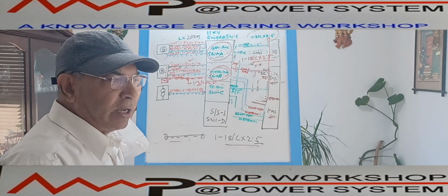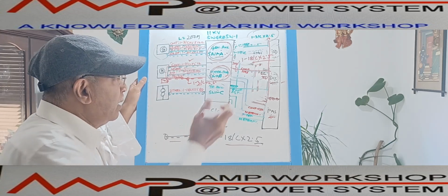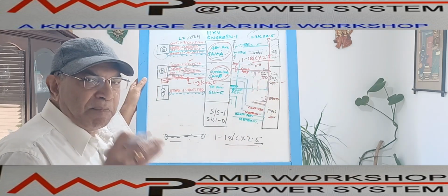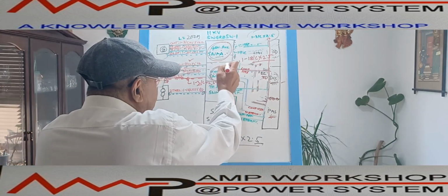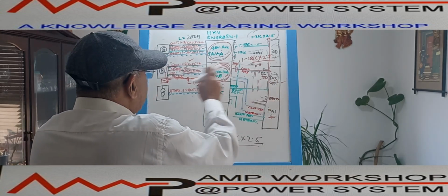What will this cable carry? It will carry breaker on-off control from the DCS, as well as various statuses of this particular panel, whatever we want to monitor in the DCS, such as the winding temperature.